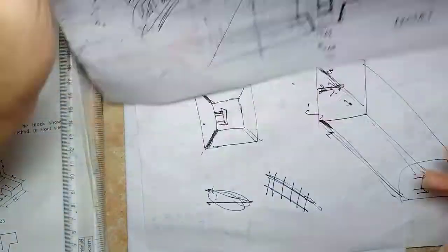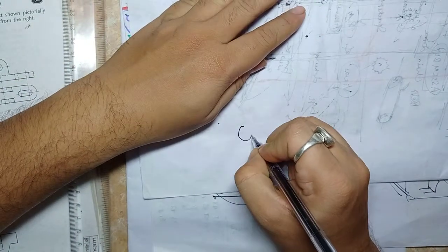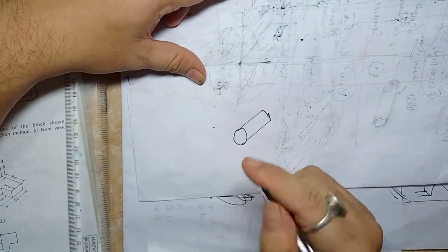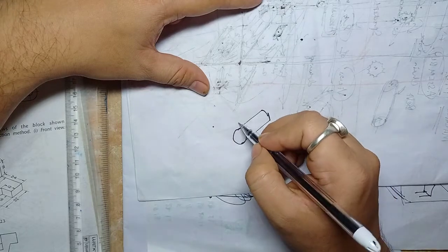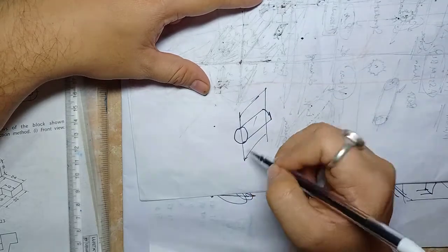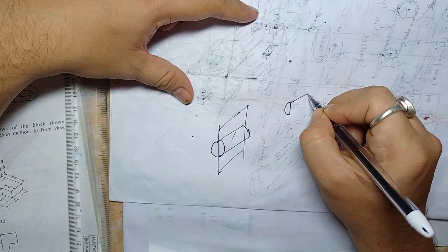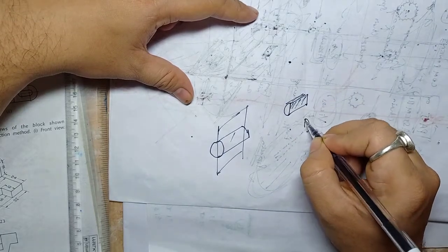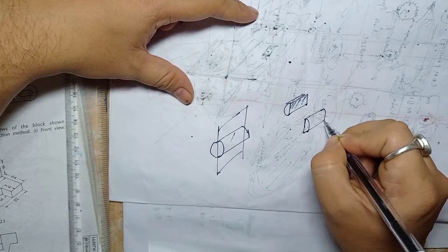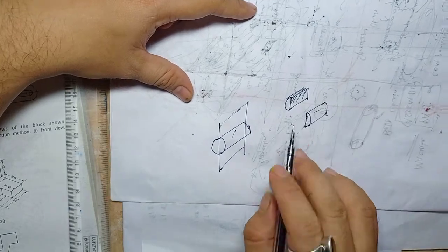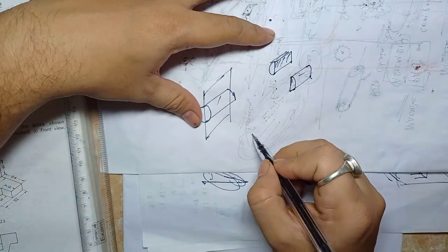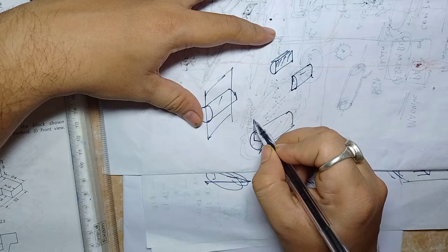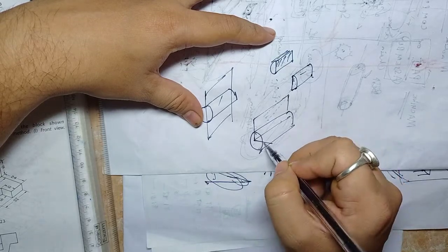As an example of sectional view, let's say this is a cylinder. If we section it completely with a cutting plane like this, one piece will look like this and another piece will look like this. Understood? This is called sectional view. And half sectional view is when you cut 1/4. Two cutting planes are required now, this one and this one.